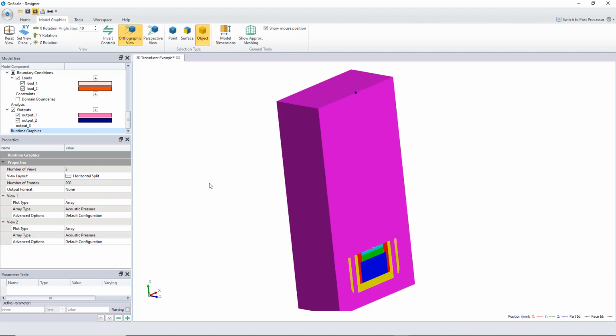If you're using the cloud, I recommend defining a low number of snapshots because this will influence the calculation and also the data size that you will have to download. So better to use 10 snapshots or something, or not use snapshots. Anyway, now let me show you with the basic option.